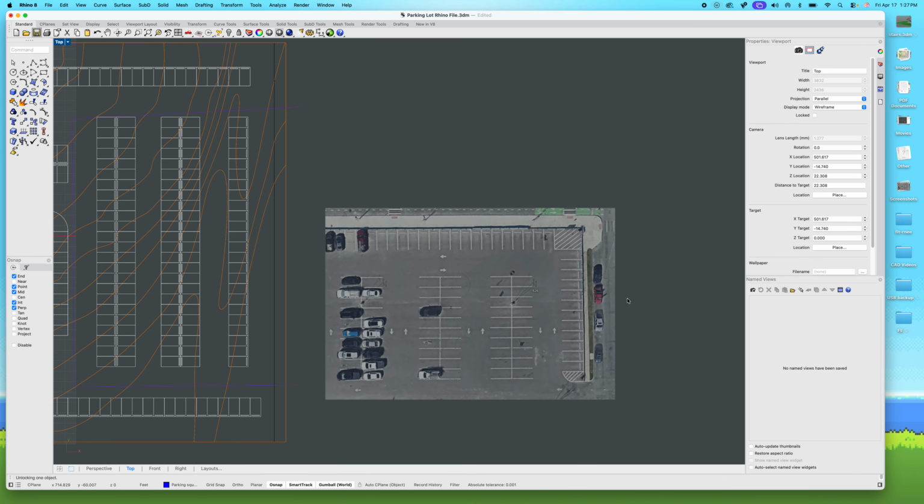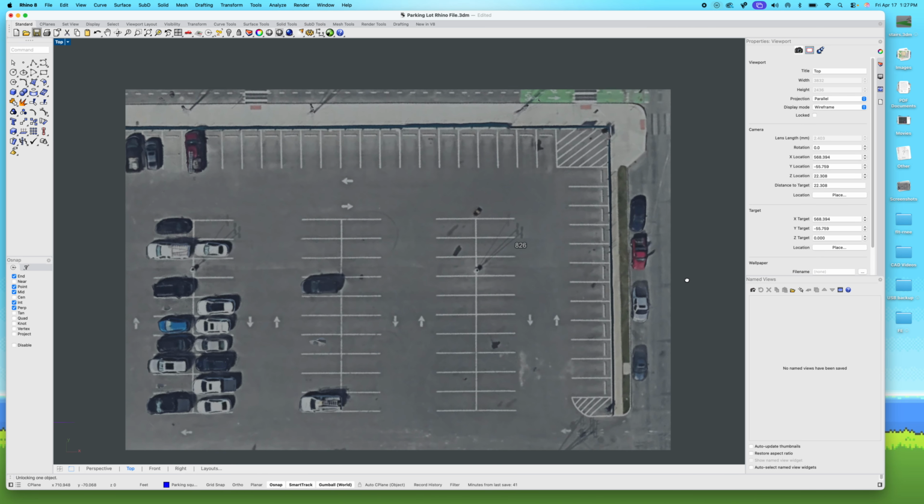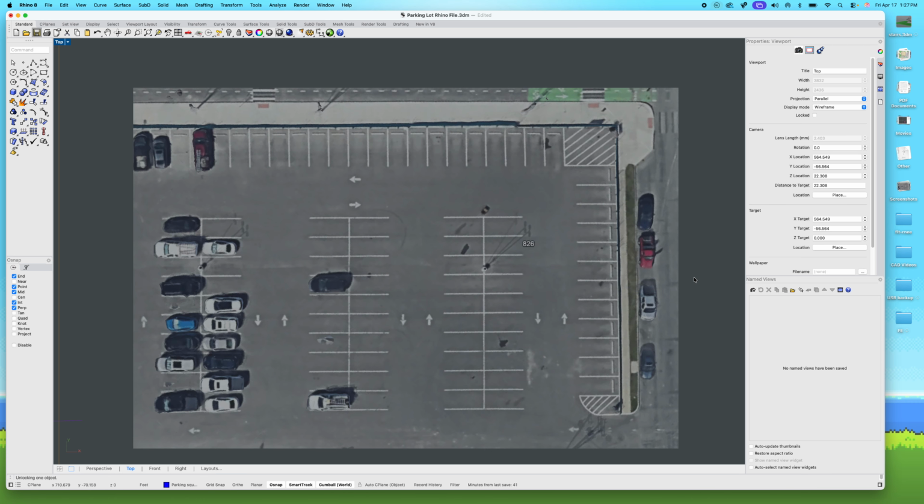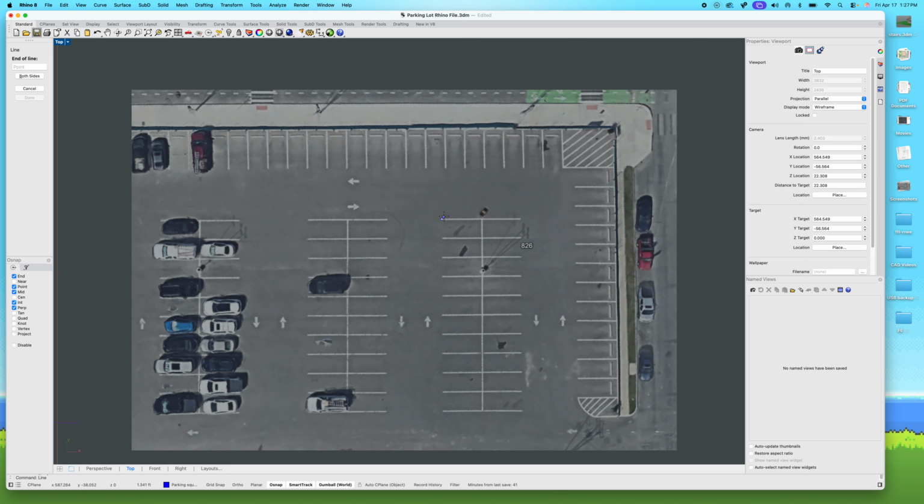I know some of us haven't even taken or even probably used Rhino yet, but I find it to be absolutely amazing. So in my case, I'm just going to draw some lines. I can type in line, and spacebar is going to reenact the same command. So if I hold shift, to be fair, I don't have to do this all day either.